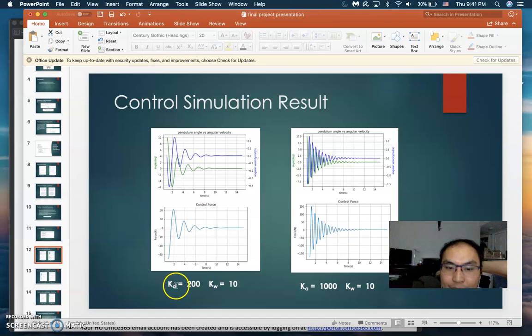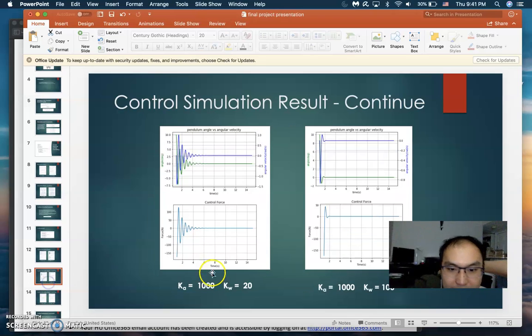As we increase the position gain, which is Ka, we increase our system's balancing performance. As you can see, the balancing time decreased from almost 15 seconds to around 12 seconds. As we increase more, we get even more performance gain. Now the balancing time has dropped to around 6 seconds. Next, we stop increasing the position gain.